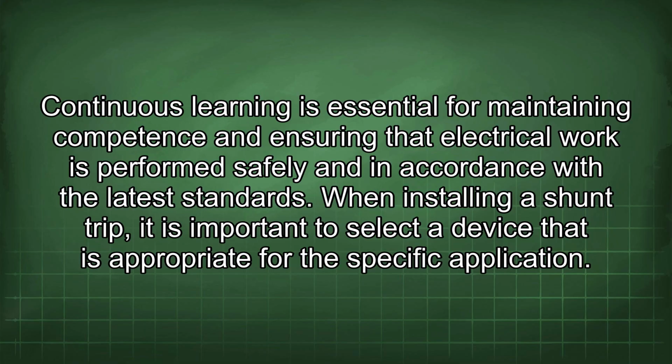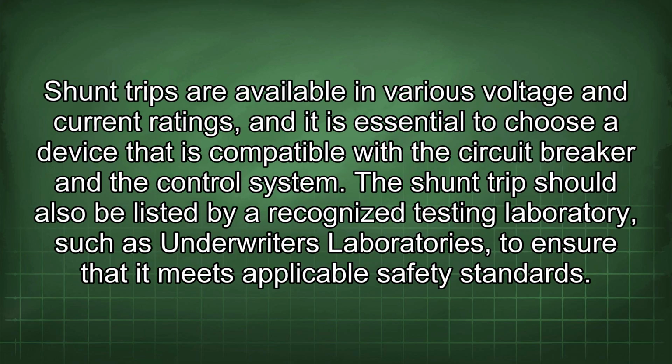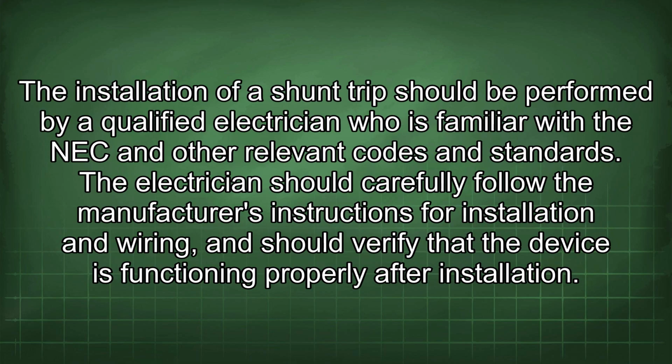When installing a shunt trip, it is important to select a device that is appropriate for the specific application. Shunt trips are available in various voltage and current ratings, and it is essential to choose a device that is compatible with the circuit breaker and the control system. The shunt trip should also be listed by a recognized testing laboratory, such as Underwriters Laboratories, to ensure that it meets applicable safety standards. The installation of a shunt trip should be performed by a qualified electrician who is familiar with the NEC and other relevant codes and standards.